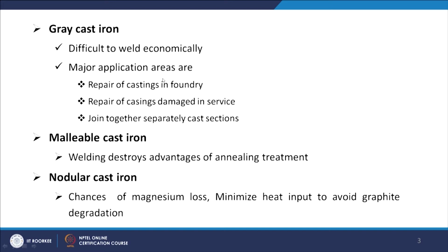If you talk about the malleable cast iron, here your carbon is again in the free form, in temper form. Here you have the quasi spheroidal type of carbon, that is temper carbon, and the way it is made is from white cast iron. Since white cast iron cannot be used, we use malleable cast iron by giving the proper heat treatment to this material.